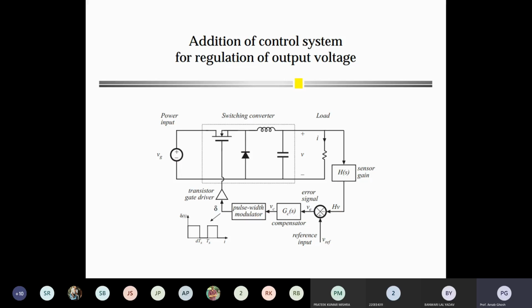There is a variety of methods used to specify line regulation. However, a common definition is this. Now you can understand the regulation expression. The line regulation is equal to delta V0 by V0 into 1 by delta Vin into 100% per input voltage.